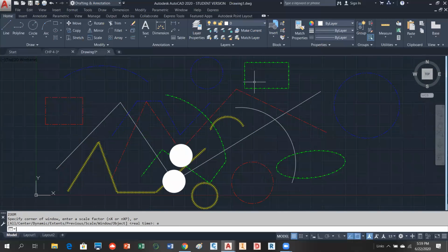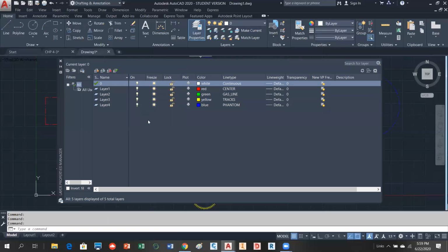So you have object properties, which are primarily these guys, and you have layer properties, which is this group right here. And again, this is the way that most people do it. It makes the most sense. It gives you the most control, the most flexibility. I will tell you, there are occasions you want to have a green object on a red layer, but not too often. Occasionally it's okay, but you're not going to use that a lot. Okay, everybody seeing that? Yep.